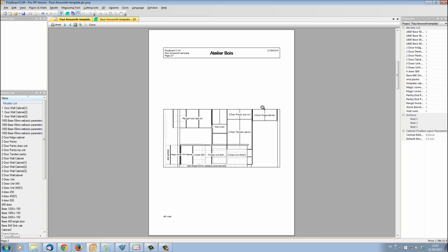wall. But I can see that I also have all the furniture in front of the right hand side wall. To get rid of the furniture in front of the right hand side wall, I'm going to create a cutting plane in my partial view.